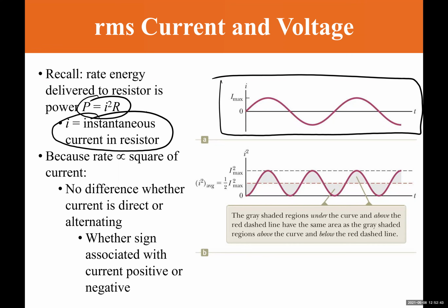But when you're doing the power over time, that means, what is the rate at which energy is delivered to the resistor? Well, what you get here is power equals, so basically I max, so it's I squared, right? So then I max sine of omega t, squared, then times resistance. Which means you get I max squared, times sine squared of omega t, times the resistance.